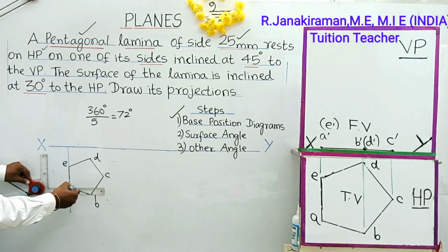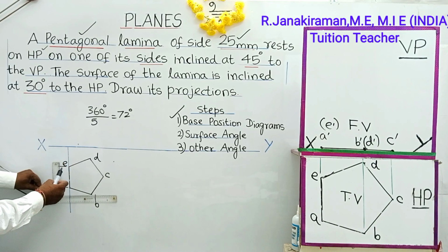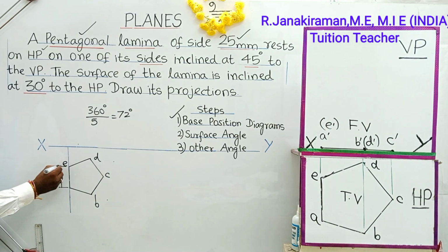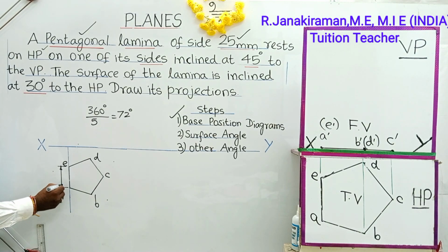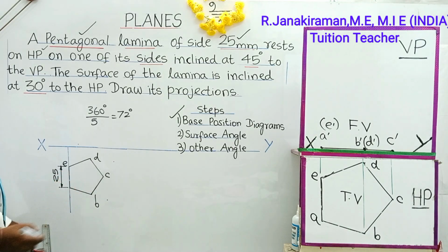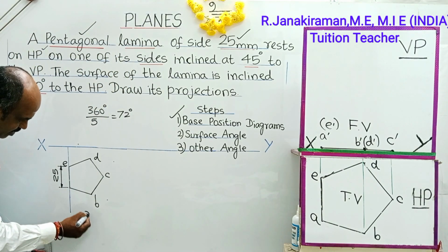Let us mark the size. Draw extension line. Draw dimension line parallel to the side AE. Put an arrowhead, shade the arrowhead, and you can write the size as 2.5. Don't write mm. Number alone is sufficient. Okay. This is a pentagon. This view is called a top view. This will be our first diagram completed.